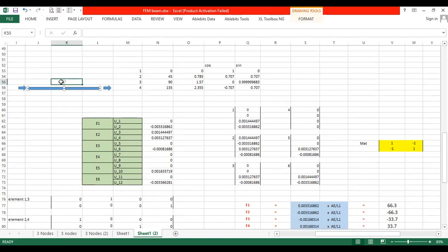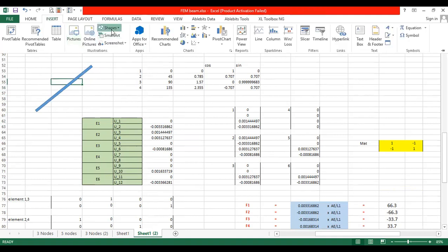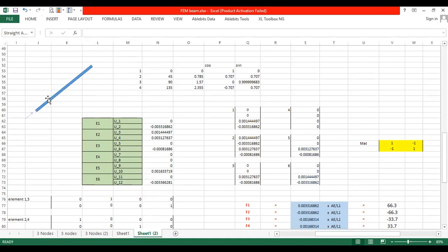If the element is angled, then you need to angle these things as well. Whatever the member position, U is always in the axial direction at the 2 nodes. This is always the first node, where the element was defined first. So you remember that this is the W1 in that case, right? W1.